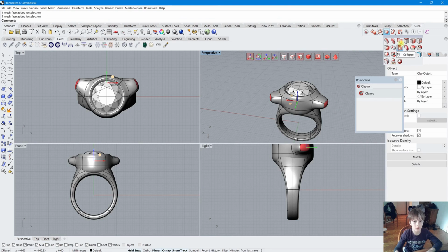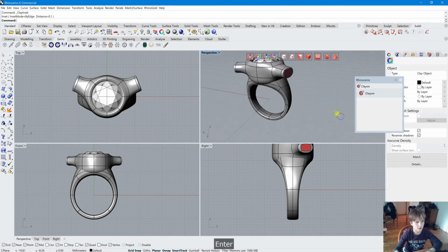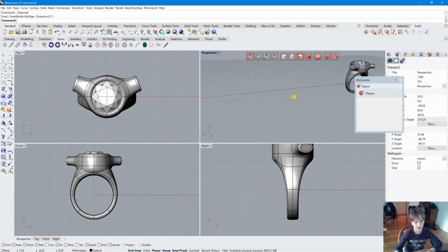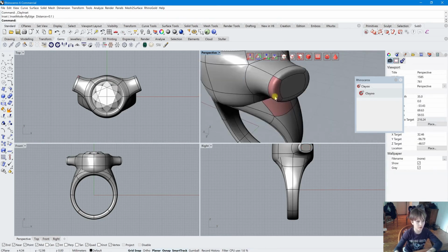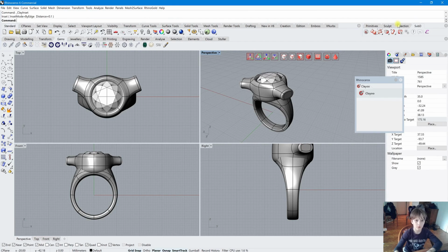Besides extrude, there are other useful tools. The inset function lets us create a smaller polygon inside the original, which is great for adding detail or making the edges sharper. Using an inset here, we can form a unique, ring-like structure that stands out because of its unusual shape. There are also additional editing options available. The rack tool can bend or conform the geometry. Then here are the selection tools, which are placed separately. The settings for these hotkeys, the settings themselves, and help.